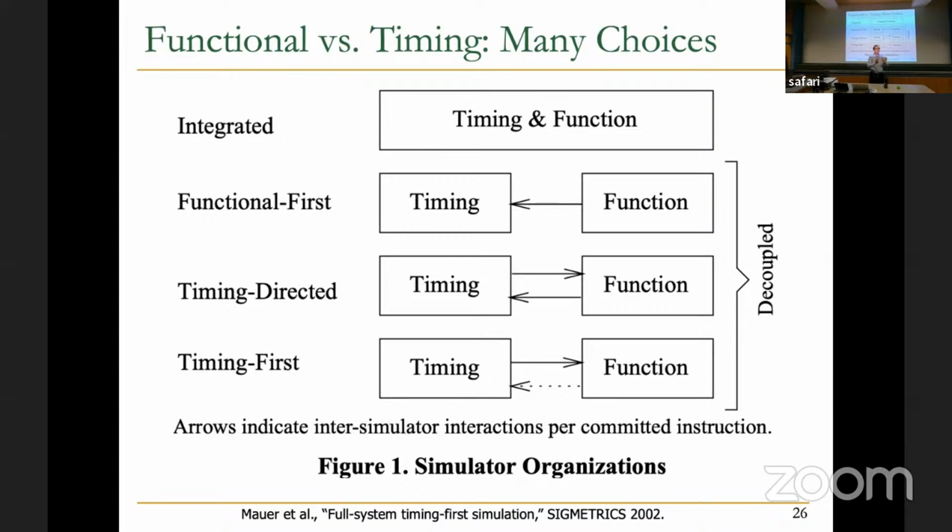If you look over here, the first thing you take is a binary. You take the first instruction, you execute it, you figure out what it does, and then you send some information to the timing simulator, and the timing simulator models it. It models the iCache, the queues in the pipeline, the out of order engine. It simulates everything that happens out of order except the execution of the instruction. Make sense? And it keeps feeding information that it finds.